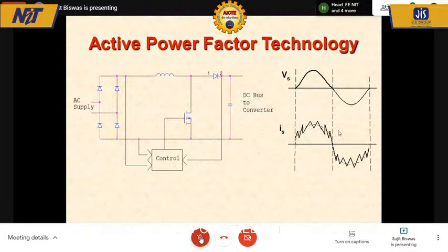And for the next half cycle, as I mentioned, I get a reversed sine wave here. It will follow, and the input AC supply current will become something like the bold waveform that is shown. It's not exactly a sine wave, but it's a reasonable sine wave with some switching harmonic superimposed onto it. That is a high frequency component. It's still there, I do agree, but the magnitude of harmonic has reduced, so the total harmonic distortion has reduced. But I have achieved the locking of the zero crossings of the current with the zero crossing of the voltage.